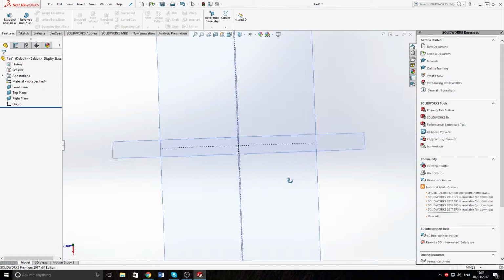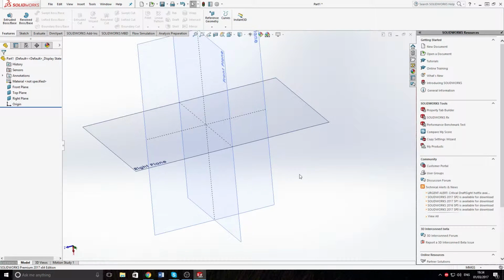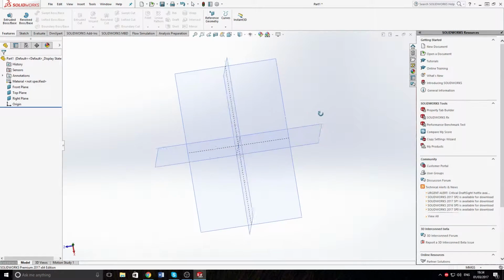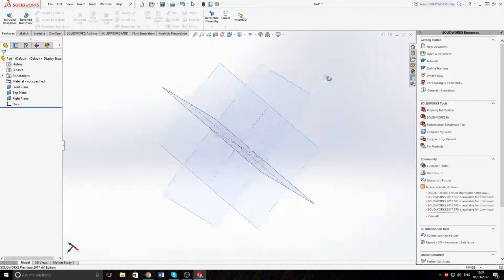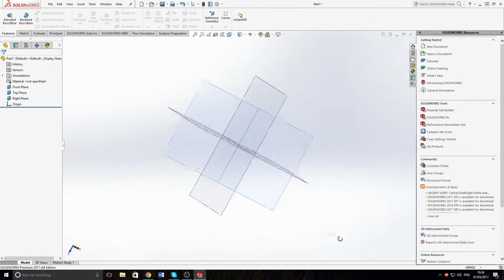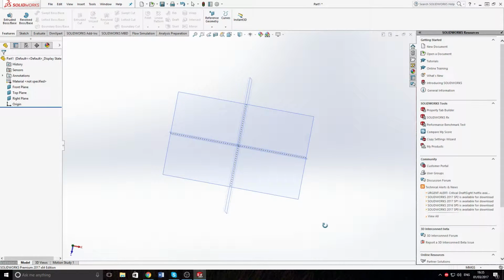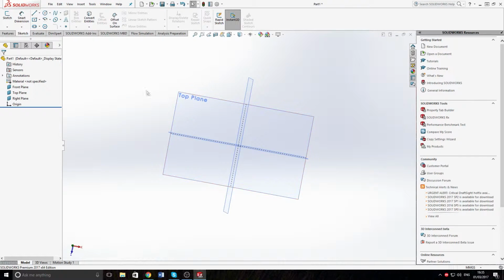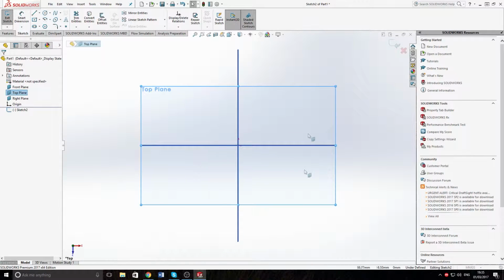So Solidworks basically works pretty much off of sketches that you can then extrude or cut or do things with, and then you can have fillets and chamfers. Okay. Basics, really. So start off, you need to sketch, so you click top plane, sketch. This will bring you into the sketching mode.